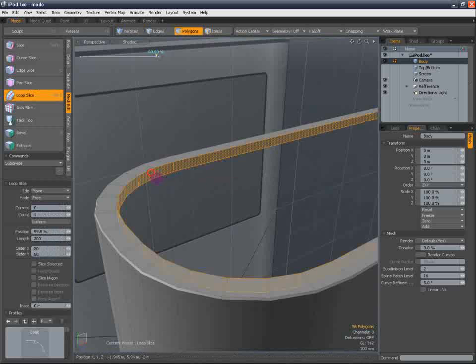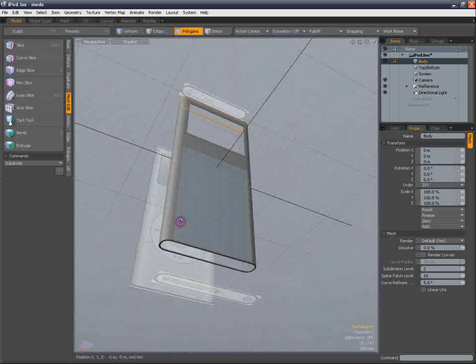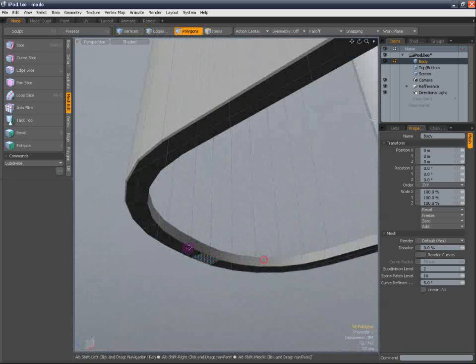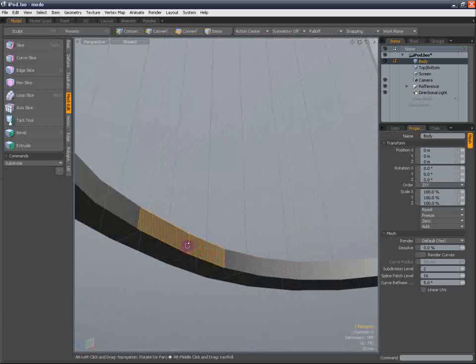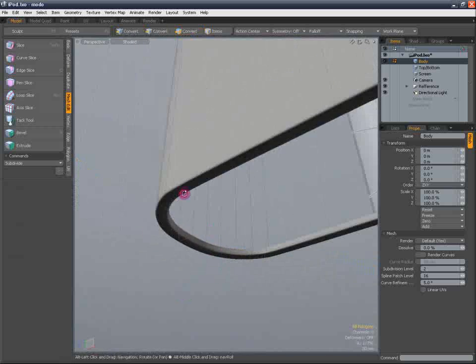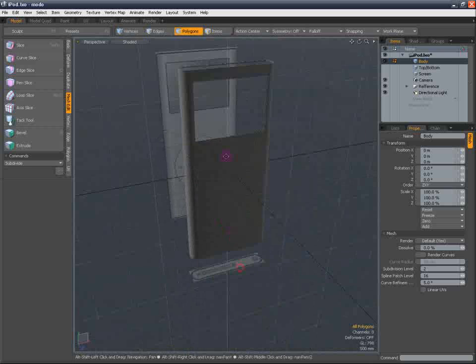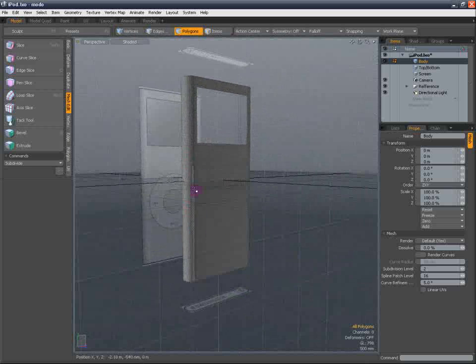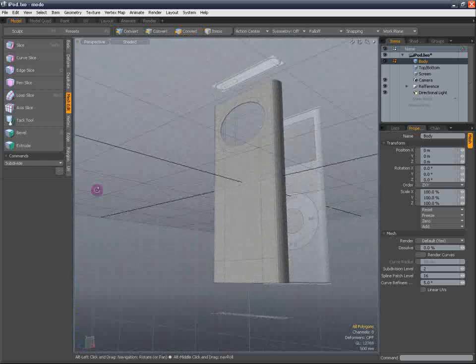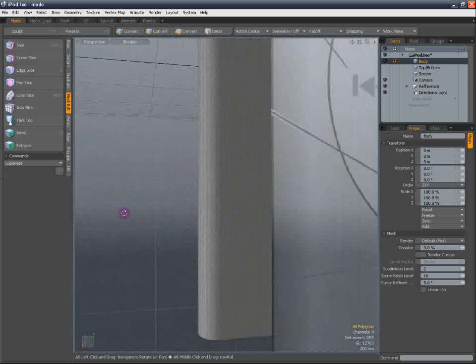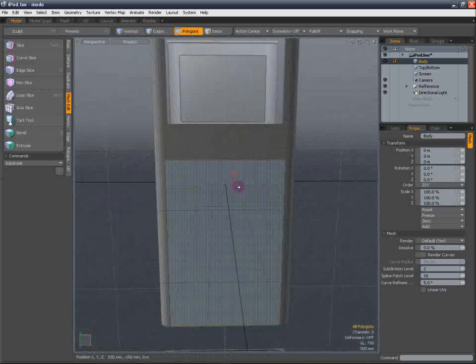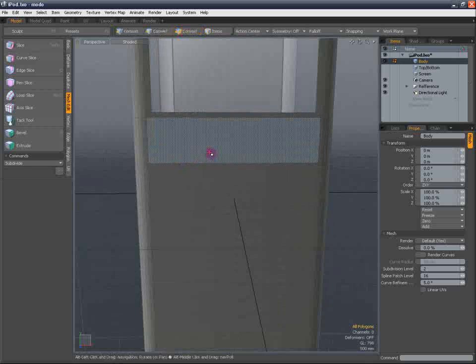And we also want to add an edge right there at about 25.5%. You can use whatever value you see fit. I'm just eyeballing it. And okay, now this distance here is kind of too big to smooth out, and our mesh is going to get a bit deformed, but we're going to fix that later when we add the wheel.